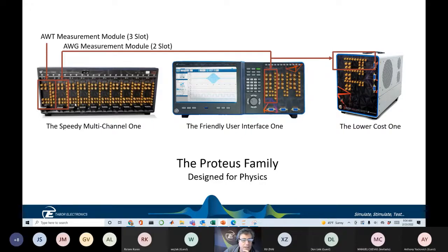This is what we call the high speed one. So if you're doing a qubit system with 32, 64, I don't know, just keep going up, 300 qubits, then stacking these modules here coherently within this chassis is the way to go. And because this sits on a very fast PCI bus, we get very fast transfer rates. So it comes in three form factors, but the measurement cards are essentially the same. Transfer speed slightly differs. This has a slower backplane than this, for example, but this has LAN control or USB-C control, where this is straight PCIe connections to your computer.